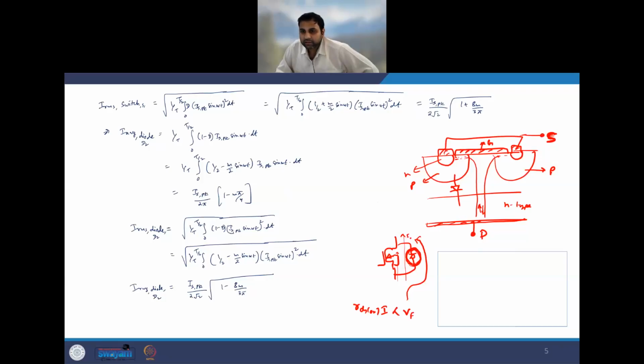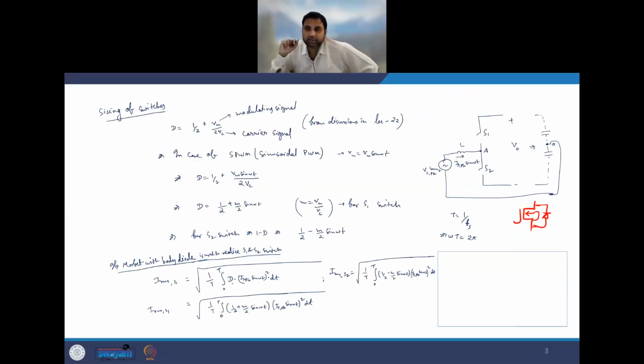voltage of this diode. So that is the reason why generally whenever the reverse current is flowing, that means from the source to drain, for the MOSFET they will create a channel, and that's when the current will start flowing through the channel. That is what generally people do, so that your conduction loss in the device can be reduced. So that is the scenario we have taken over here.